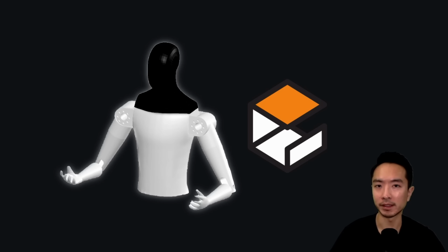So the main idea is this. We have ROS2 control, which is responsible for the motor command. So the ROS2 control can be used to control position, velocity, or torque commands of the robot. And Gazebo is going to be the simulation environment that has realistic behavior such as physics. So you can have the actual weight of the robot to have a realistic torque estimation. And there's additional features you could add on, such as friction, to get even more realistic things. But for now, we're going to take a simplified case and just try to simulate the TeslaBot in Gazebo with a basic gravity setting.